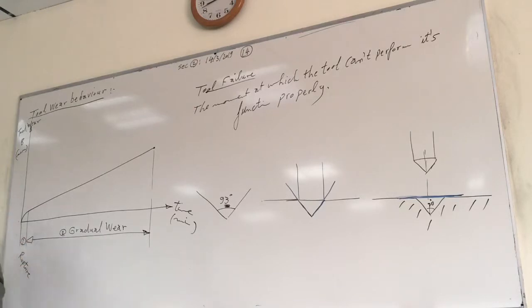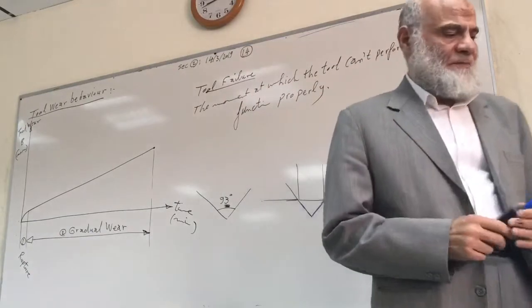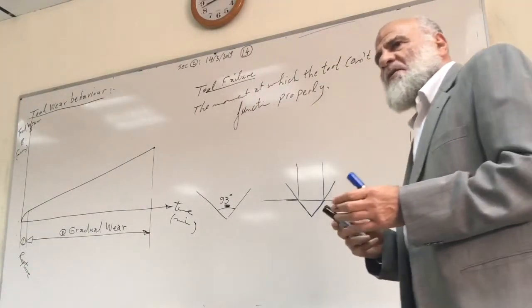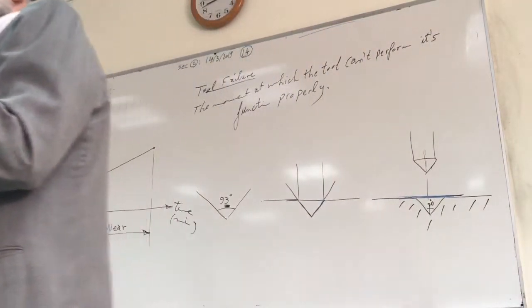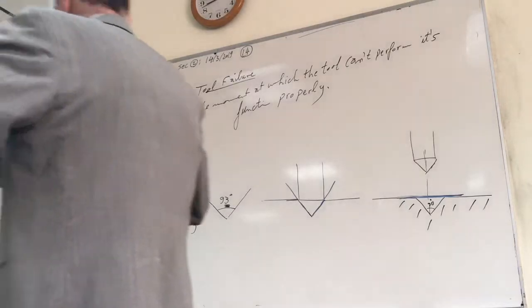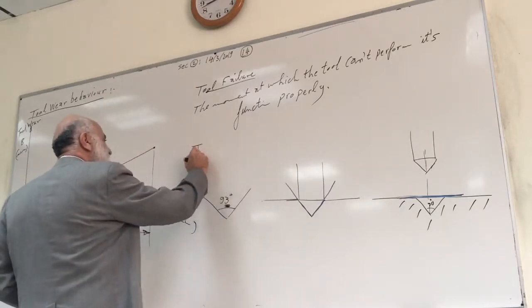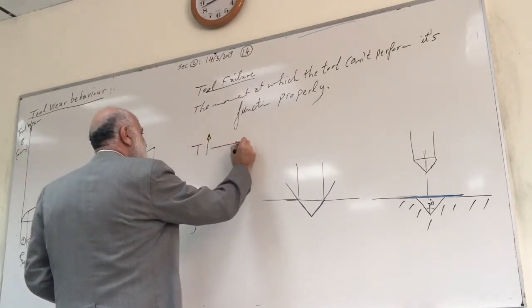What will happen with continued cutting? What happens to the tool? You know, temperature and heat generation will be given to the tool and to the workpiece, but the workpiece is lucky because it rotates in the air and cools down. Yes, it cools down, temperature is normal, but the tool doesn't move in the air to be cooled. Therefore having what? High temperature and accumulated heat. The temperature keeps increasing. And when temperature increases, what happens? Take it one by one.